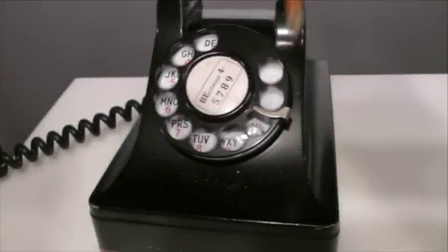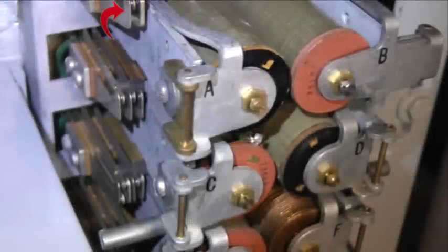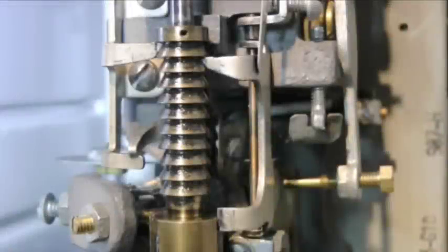As the dial continues to return, the second pulse begins and opens the loop. This releases the A relay, while the slow release B and C relays remain operated. This causes the vertical armature to reoperate, and its attached vertical pawl to re-engage the vertical ratchet. The pawl pushes the vertical ratchet up one step, along with the shaft and all of its attached apparatus. The wipers move vertically upwards by one more step, which brings them in line with level 2 of the bank terminals.